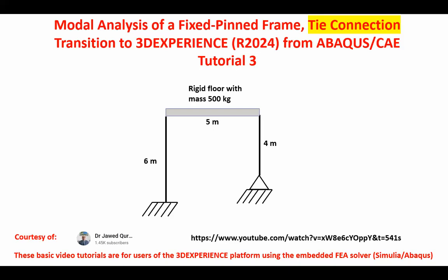In tutorial 2, I did not actually draw that thing in a sketch. What I did, I created 3 wireframe lines in space. 2 vertical ones, which are representing the column, and a horizontal line, which represented the beam. Now, when you mesh those things, in tutorial 2, I asked for any 2 nodes which are within a certain tolerance of each other to be merged.